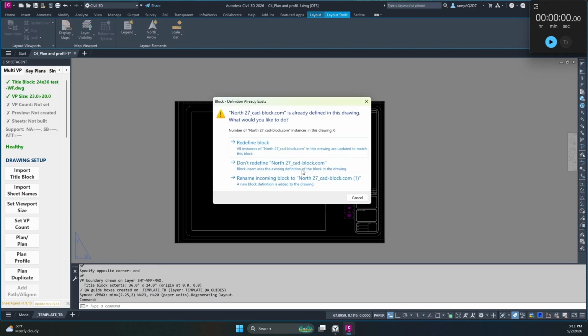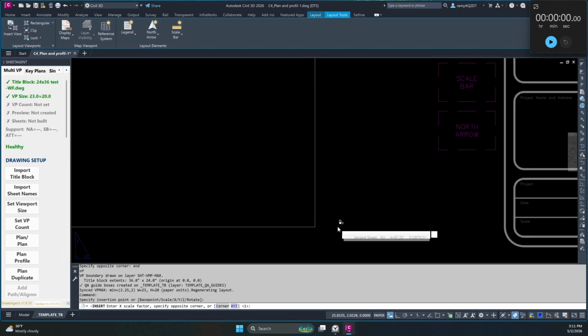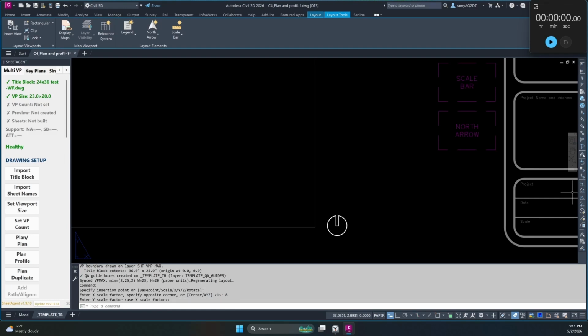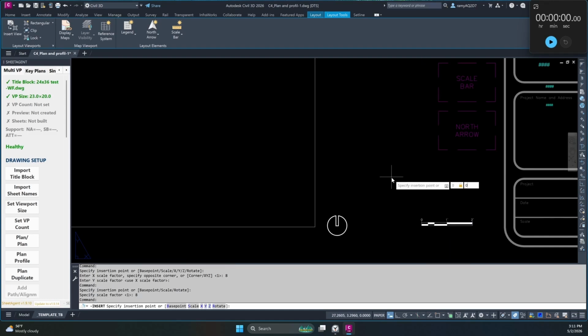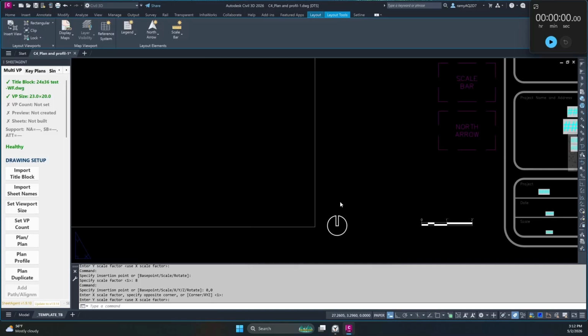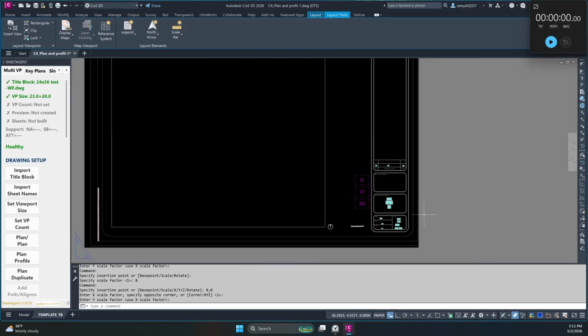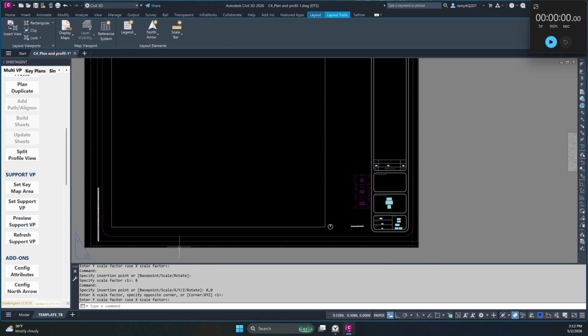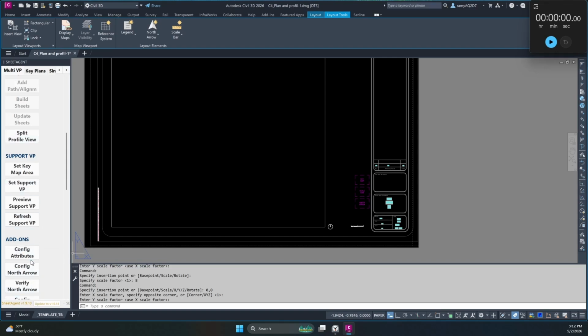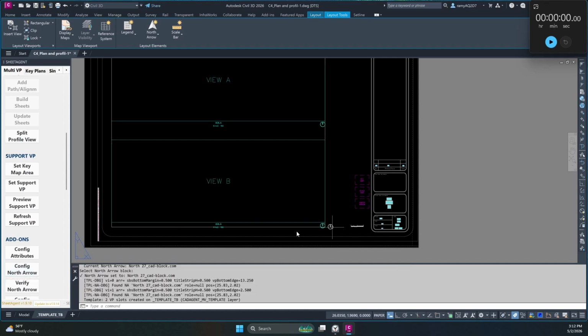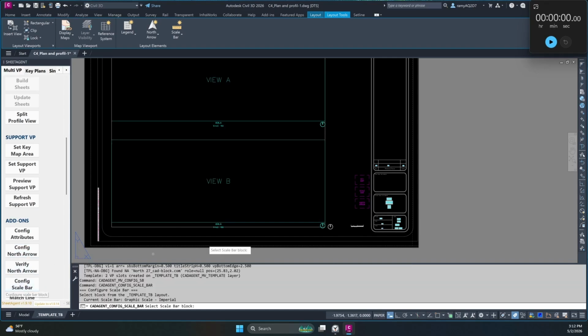For this one, we're gonna insert the north arrows and scale bars from the beginning, since we've seen how that works if we forgot. So now it's the same, and it's exactly applicable across all functionality. No matter where you are in whatever tab, multi-viewport, single viewport, you can always add those at a later stage. So now we add them, just a reminder that it's always on the title block or the template title block. This is where insertion comes in: configure title block, configure fields, configure north arrow and configure scale bar.